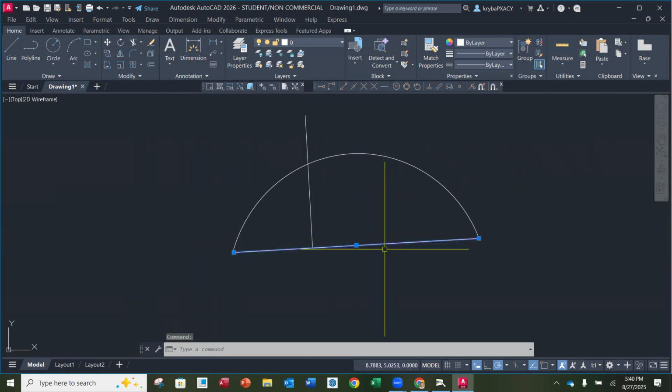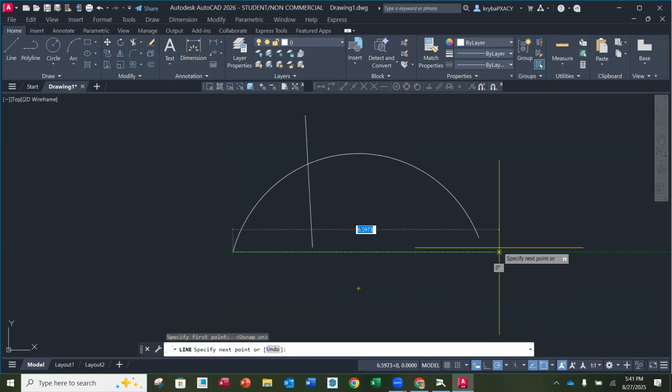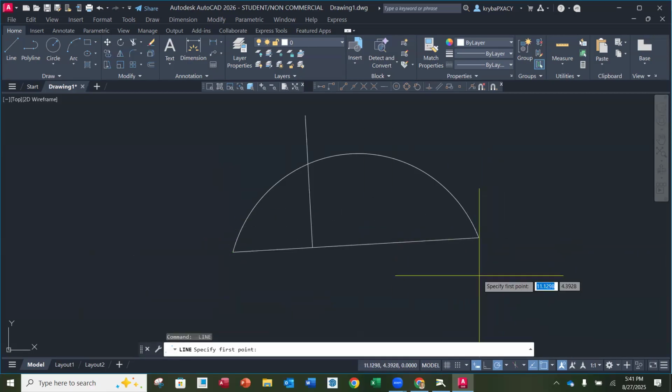Okay. So that's why it's always better to have really good geometry from the start. Okay. So using your object snaps becomes really, really important. I'm going to turn those back on. And that's why running object snaps, then you don't really have to think about a lot. They'll just automatically happen. And so really for not only you and not being that person, okay, that everybody's like, oh boy, now I got so-and-so's drawings to deal with. I might as well start over, but it's really for down the line. These files are used in more than one place. It's not just a picture we're creating. It's actual geometry.